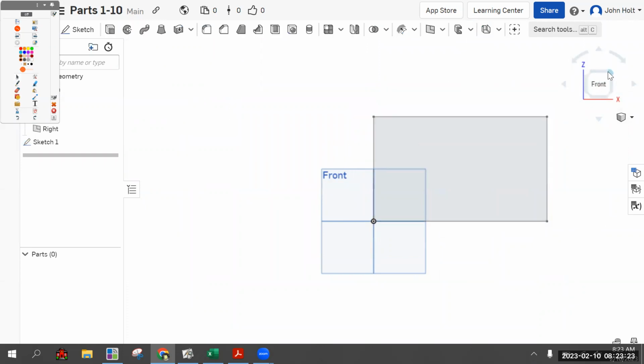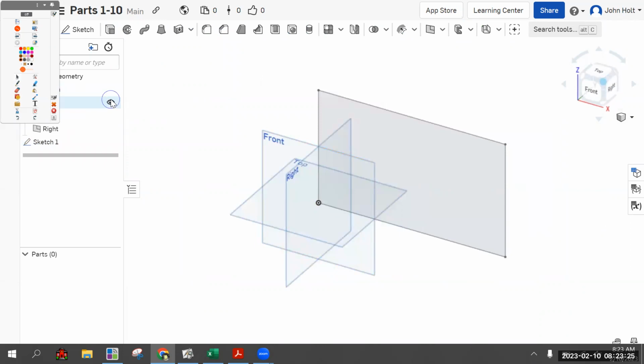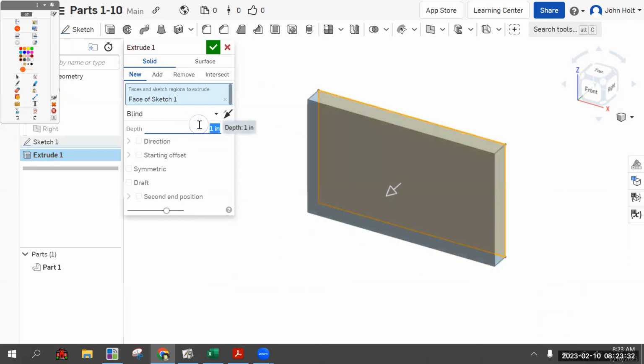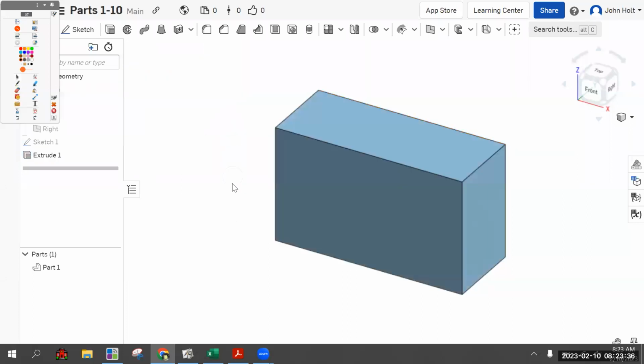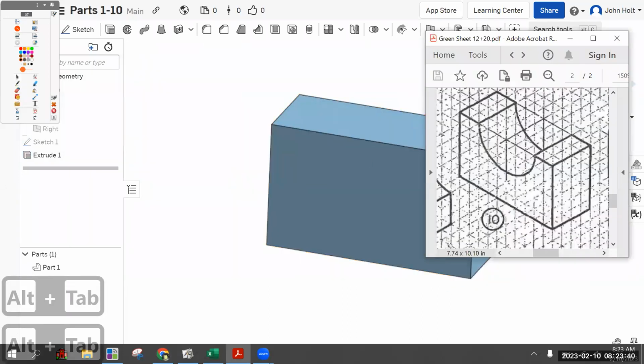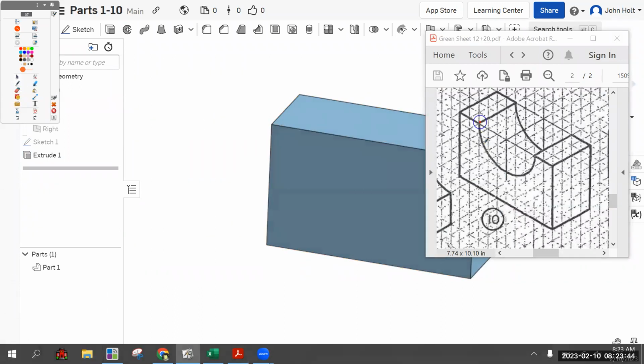Finish sketch, corner, origin point and planes, and extrude, choose that, extrude 4. Okay, and the only other part feature is a rounded semicircle cut extrusion. And we're going to do the same thing as before.